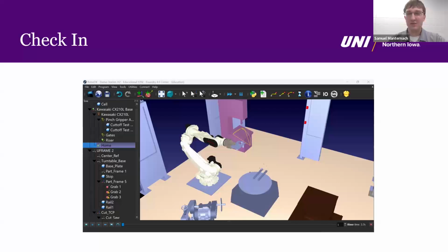So in this case, you're going to want to be using a lot of lookups in tables for what's an appropriate feed speed for when you're cutting each of your materials and for each of your material thicknesses. In the case of a bandsaw blade, you're going to have to be very particularly aware, just because you're having such large section thicknesses, that it's going to affect the rate at which you can cut and the rate at which it can excavate all of the chips that it's making while you're cutting.